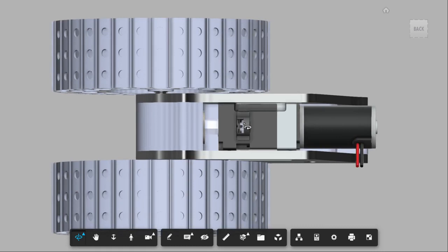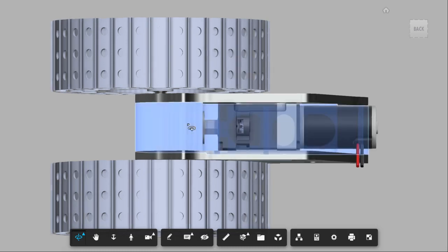It's a 100-to-1 gearbox that basically steps up the torque from this DC motor. So as you know, as you step up the torque, the angular speed is also going to step down by the same amount. So as we step up the torque 100 times, we're going to lower the rotational speed 100 times. Now, another thing we have hidden in here,